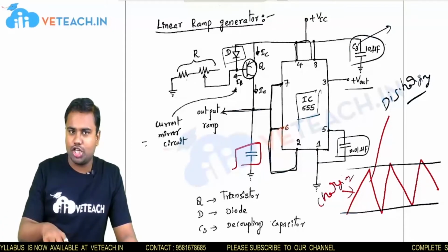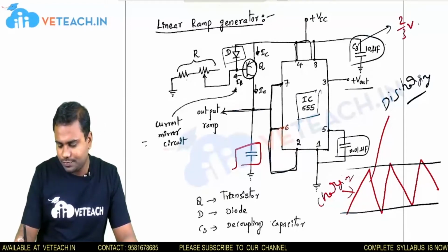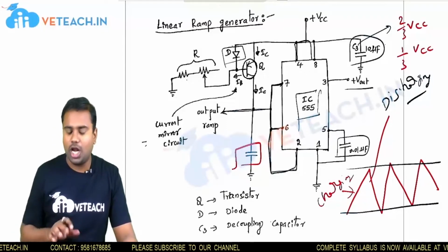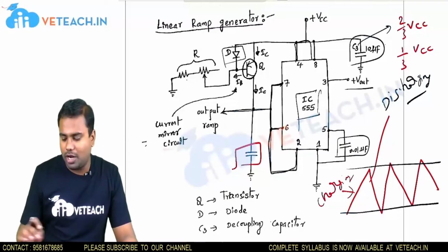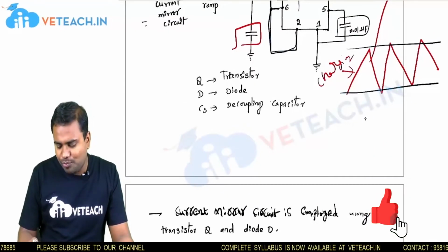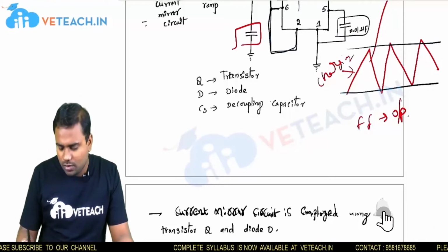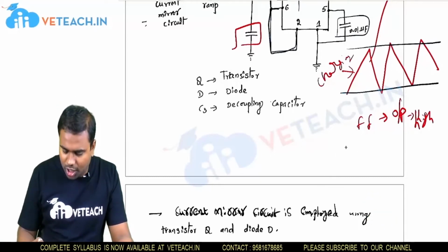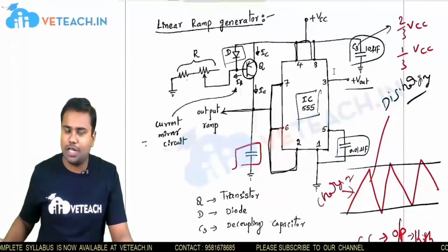We all know that inside the circuit we have the threshold voltages, like 2/3 VCC comparator voltage and 1/3 VCC, in the internal circuit of the IC 555 timer. We are going to work with this 2/3 VCC and 1/3 VCC. Basically, we all know that the flip-flop output will be high at the starting point. If the output is high, then what will happen? The charging path will be in the capacitor, and this will be in the discharging mode.